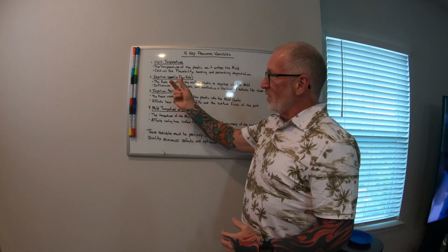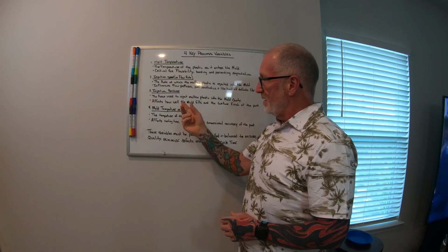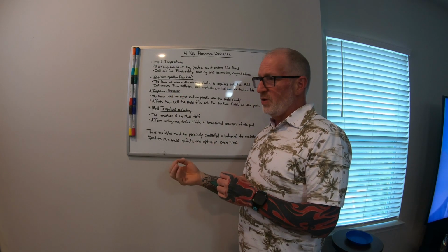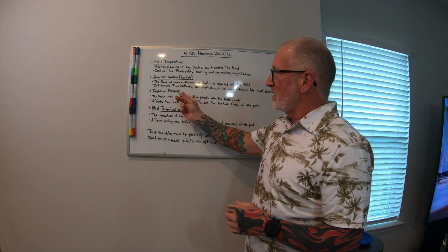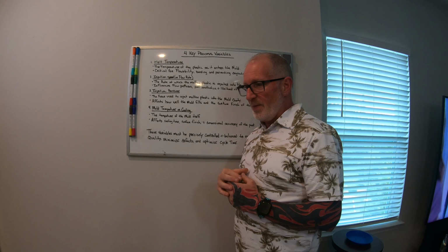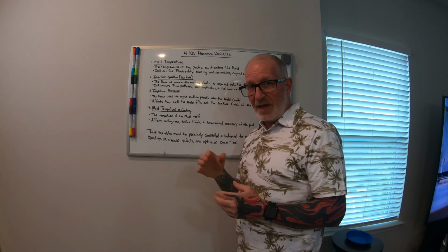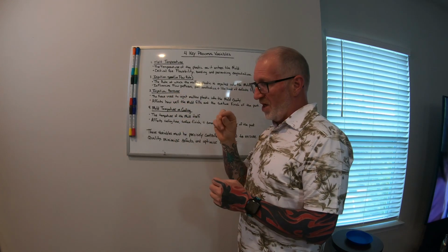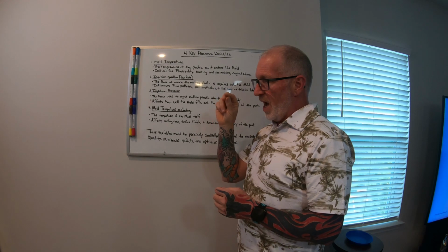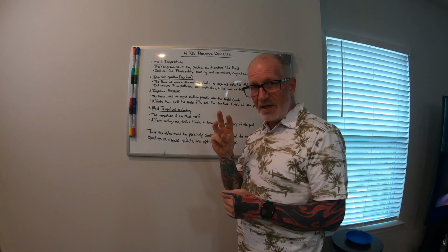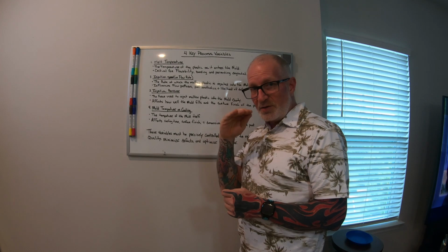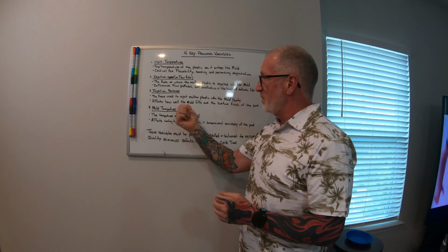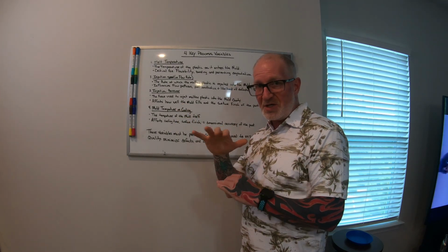So what I do is, once I get that flow rate where I want it to be at, I work on the pressure. I gradually bring it up. Once you get to that point where you want it to be at, most people do what they call a gate freeze study. That'll tell you how long of a time you need, plus the pressure basically, because you're going to go in increments. So you do your time, you'll go 1 second, 2 second, 3 second, 4 second, 5 second. You'll take all those parts and you'll weigh them all. And then that'll tell you exactly what your time should be for your injection time,